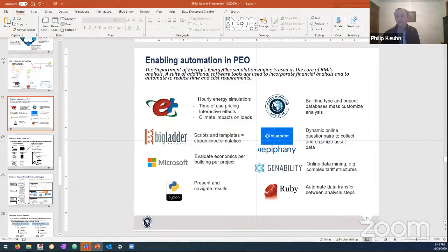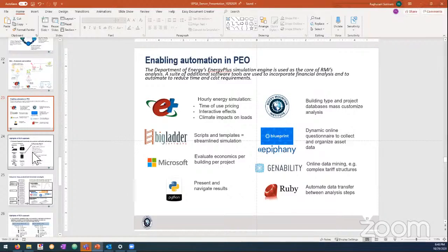We don't use a blended utility rate. If there's a ratchet or a block or a time of day demand rate, all that's built into the model. And for a lot of our grid interactive solutions, we're aiming to look at that price structure and adapt accordingly using EMS logic. Cool, that makes sense. Thanks.